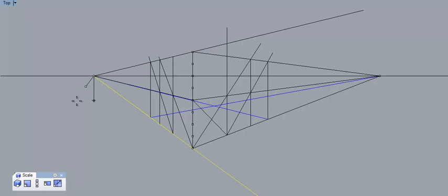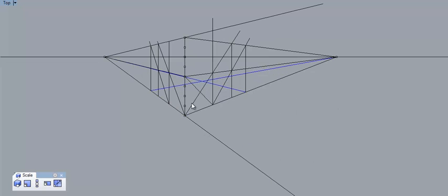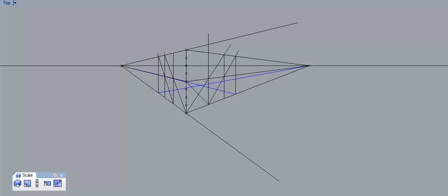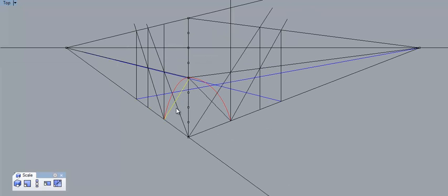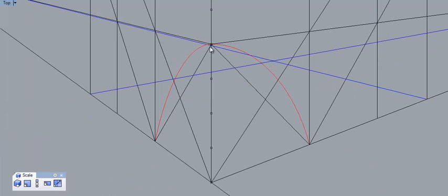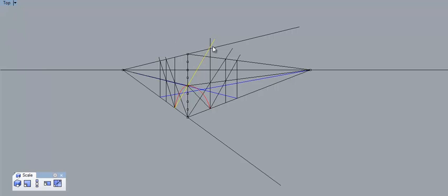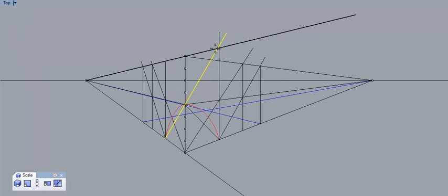Take this guy, project him out farther. And you can see, based on how I set this up, this is going to generally get distorted relatively quickly. So hopefully we're not projecting out too far forward. Okay. So then from there, I'm going to go ahead and take this, and from our depth guess, because that was where we made our initial depth guess, so we don't compound our errors, we only need to make 2 depth guesses. We're going to do the opposite catty corner there, and we're just going to draw from that corner in through this corner here. So from there, we can take that, we can extend that line, and that's going to give us our intersection. And pull that line down.